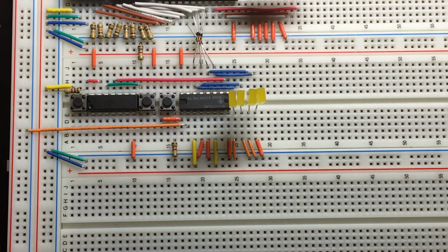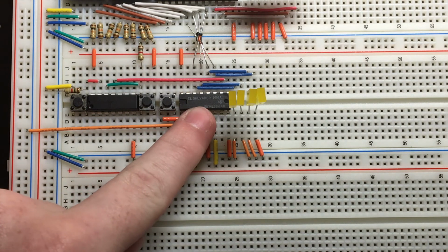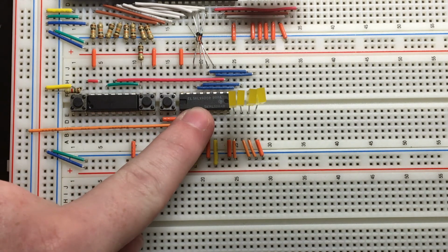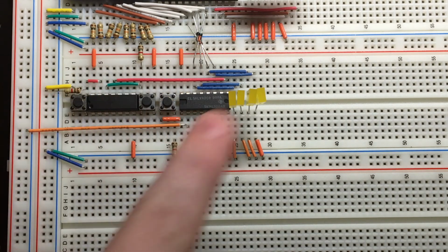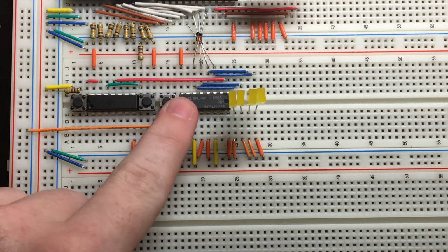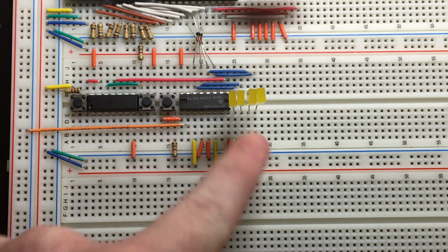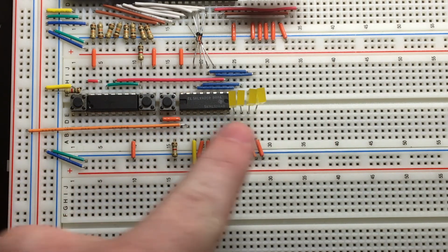So moving on, this is our program counter, and it will take in a clock pulse and output what the address is that we discussed earlier in the code. So there's a couple of things here. This is the SN74LS161, and there are 3 different buttons here and 4 LEDs. So this first button is a clear button. It will reset all these LEDs to off.